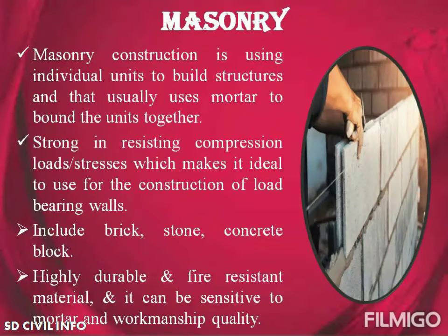The next one is masonry. Masonry construction is using individual units to build structures by using mortar to bind the units together. These are strong in resisting compression loads or stresses, and this property makes it ideal for the construction of load-bearing walls. Masonry includes brick, stone, concrete blocks, etc. These are all highly durable and fire-resistant materials, and they are sensitive to mortar and workmanship quality.